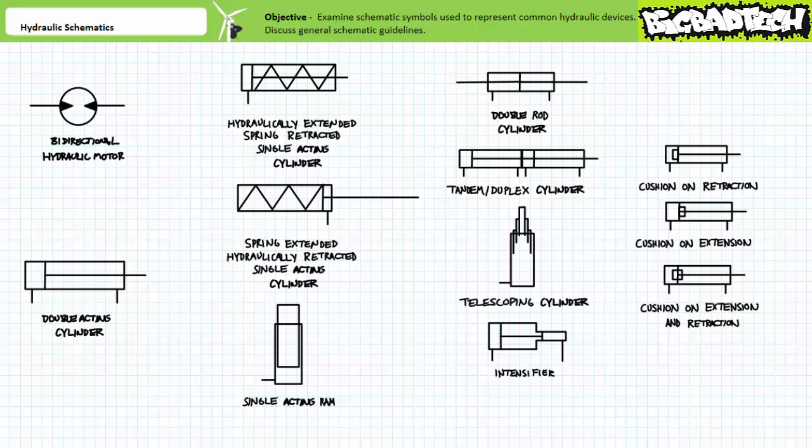Single-acting cylinders don't always require a spring to passively perform the opposite action. Consider a ram, basically a single-acting cylinder with a rod so large it has no rod end functional area. To extend a ram, pressurized flow fills the cap end. To retract the ram, the cap end is slowly drained and the weight of the lifted object passively retracts the ram. We'll discuss flow control methods and counterbalance valves in later lectures that allow the controlled descent of a lifted object.